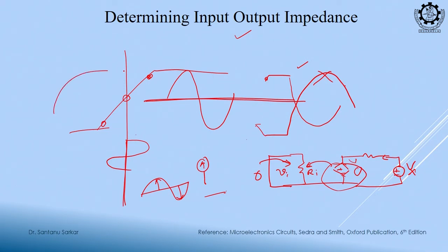How are we choosing this Q point? We are solving the transistor plots, we are solving the current through the resistance, and wherever they are crossing, that is my possible solution. From these solutions, we will see which one is coming in the middle. That voltage and that current should be my DC value.